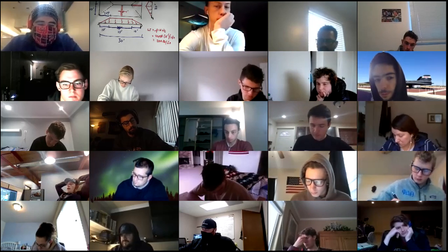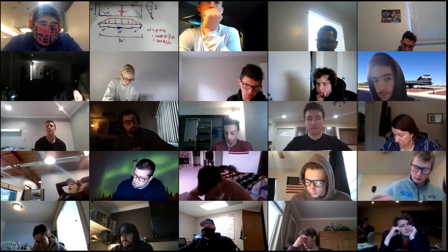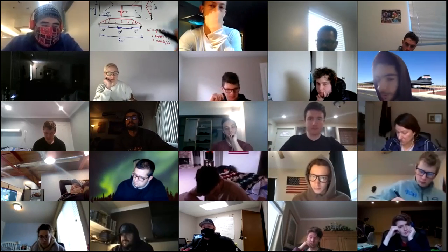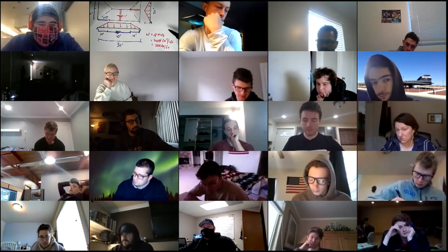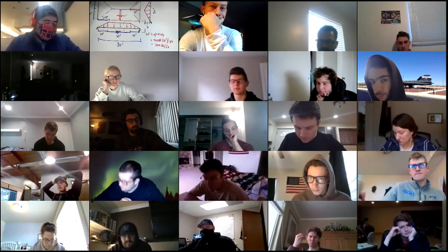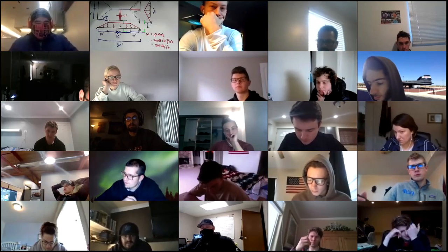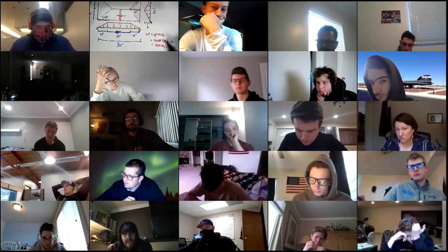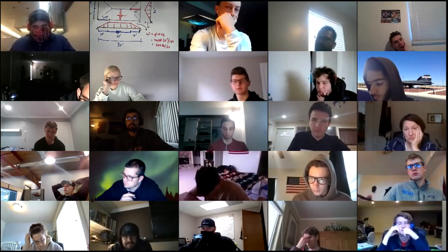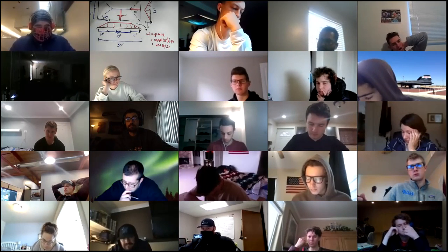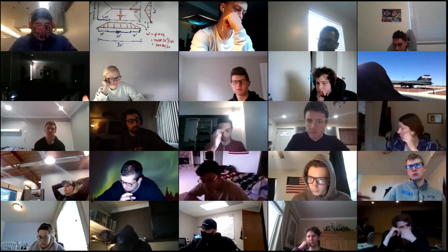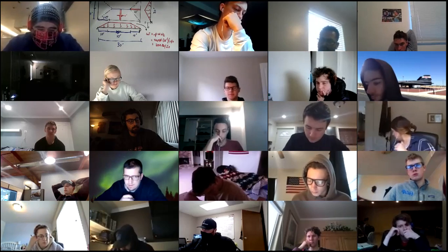Now, because of the 45 degree wedge, the magnitude here on the straight triangular load is going to be the same one, right? Because that's also going to be 10 foot, and it's the same pressure. So we're going to get the same magnitude for both of those. And I can't see how that would ever change. That would be typical all the way. So that's how you deal with two-way slabs.